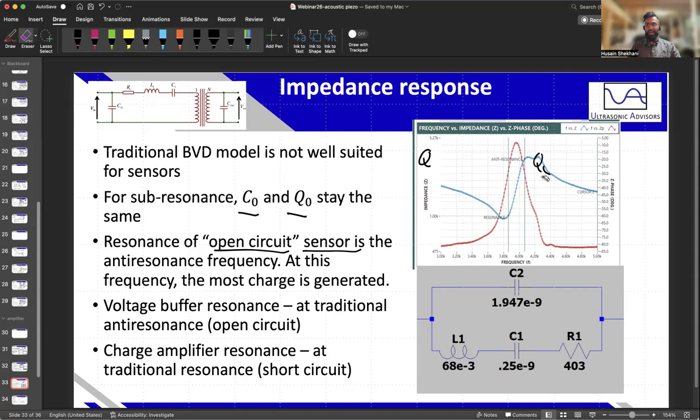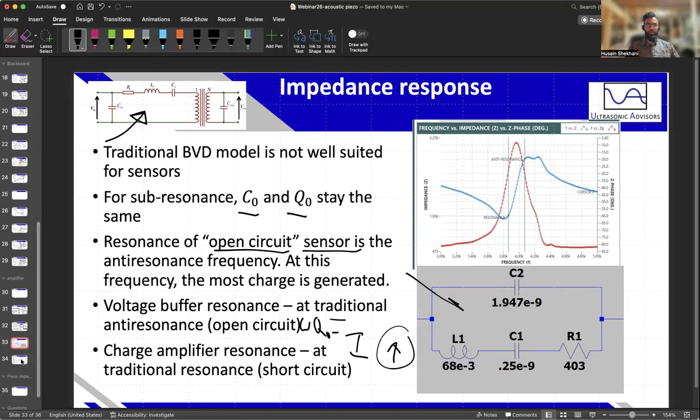So this response is not exactly appropriate because you're putting in a force, and you're getting out a voltage. So there's a conversion needed. But in general, you would actually need to modify your current generation source, because the generation of charge, or of current, would be different. It wouldn't be this model. It would be more similar to a transformer model, with voltage and current being represented a bit more. You take it one level of abstraction higher in order to get more fidelity in how you use it. But in most cases, for a DC device, you can work with your capacitance and your charge generation from a current source.